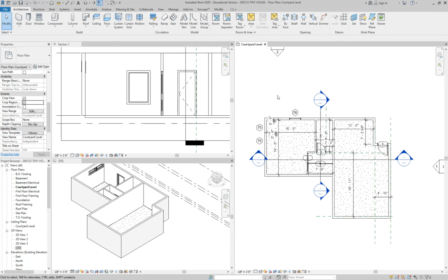Your graphics card is just having a hard time. You've done it right, it's just shading it weird. Wait, look in your section. Are you sure there's not another floor there? Zoom in on your section for me. There's a floor there still. Yep, you just had two floors. Delete it again. Okay, hit Control Z. It's really just a graphics card thing. You're okay. So the whole thing is selected.